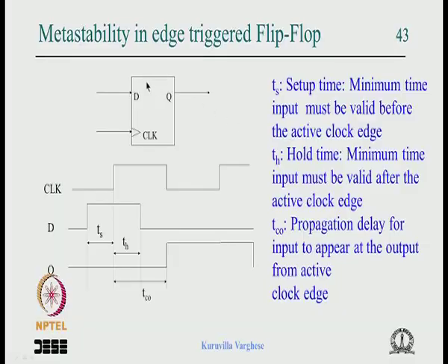So let us run through the slides we looked at in the last lecture. We know that in an edge triggered flip flop, for the data to appear at the output from the input, the data has to satisfy some timing requirement with respect to the active clock edge. The data has to arrive sometime before, that is called setup time. Not only that, it has to remain at the input after the clock edge for a while, that duration is called hold time. If that happens, then from the clock edge, with a delay, the output appears.